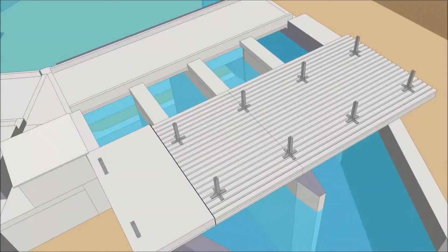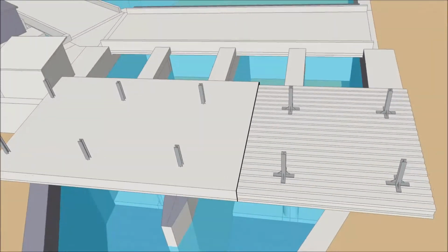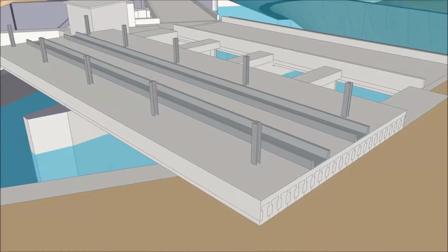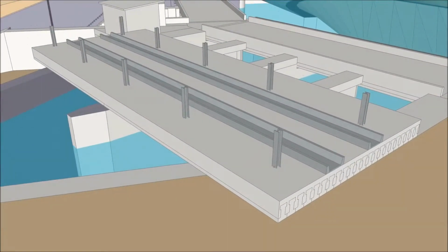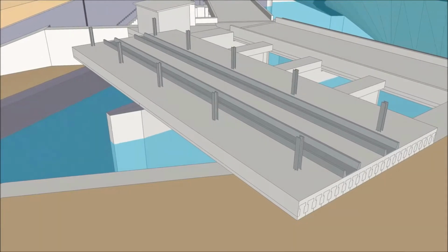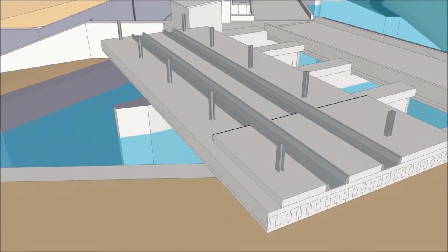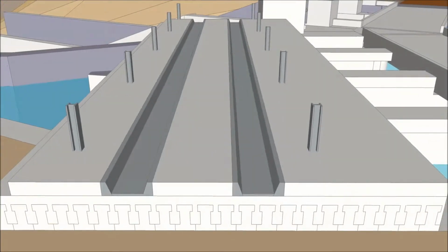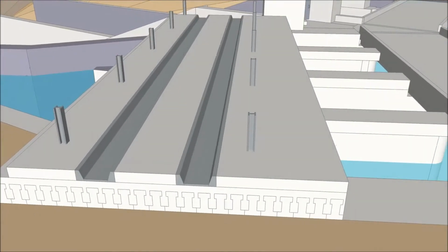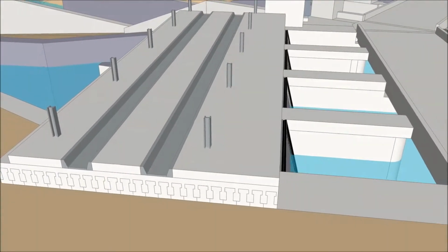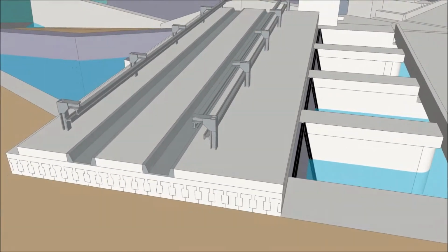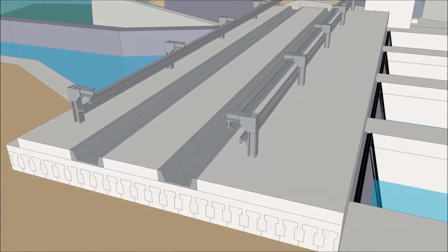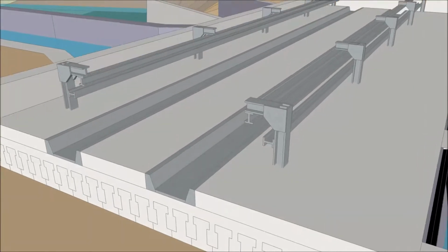Once the concrete is set, the tread track guides will be installed. These track guides will maintain the travel alignment of the working machine. Then there will be another concrete pour, followed by the installation of the steel guide rails. At this point, 2 of the 3 components of our guidance system will be in place. We have the tread track guides and the guide rail assembly.